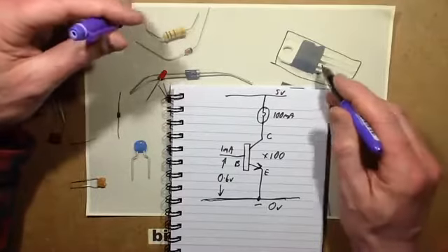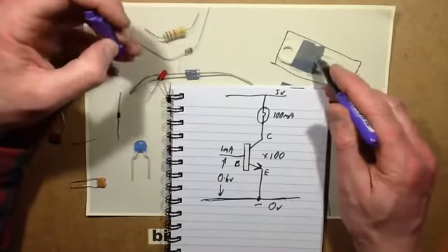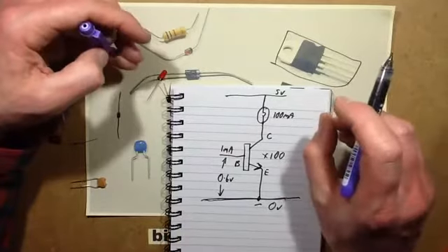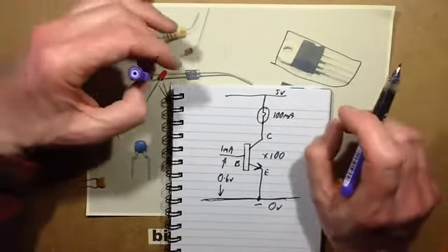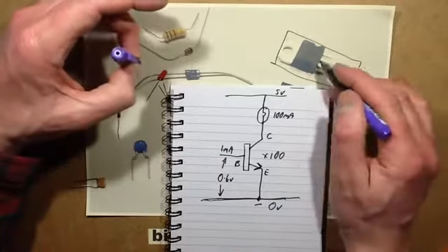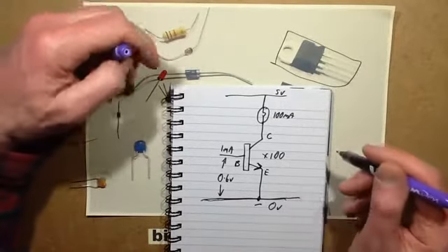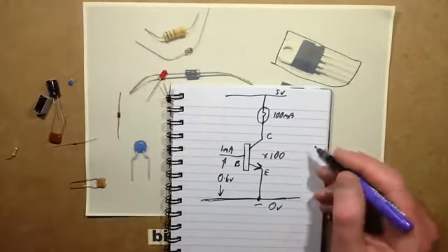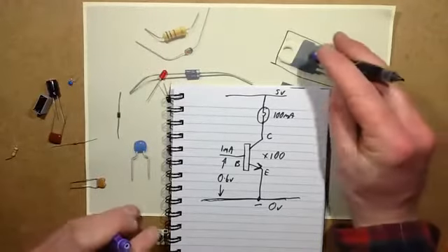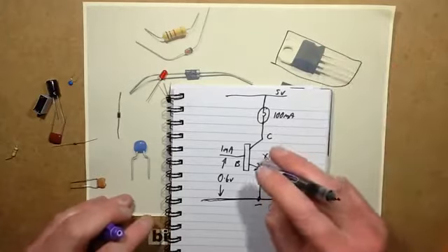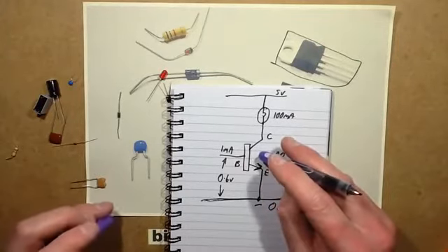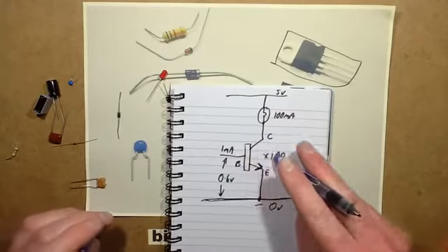They also have an extremely sensitive input, but they generally require a much higher voltage on their gate, as they call it, to actually turn on. But the current flow that's required to turn these on is virtually zero. It's a sort of capacitive effect. They're quite amazing things. You also get a hybrid. MOSFETs are not as robust as the traditional, let's see, bipolar transistor like this one.